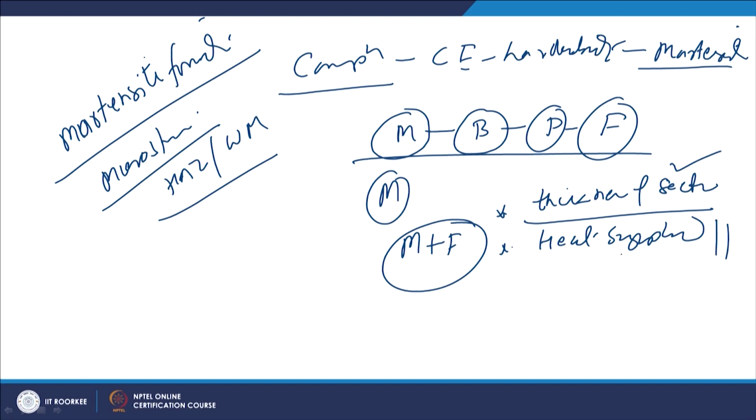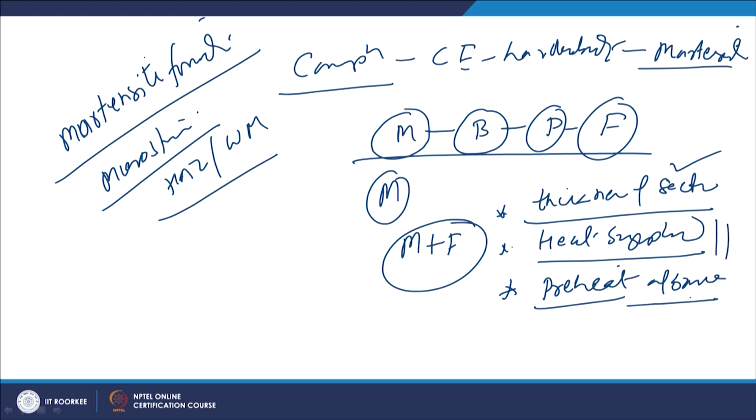On the other hand, it requires greater heat input, and higher heat input in turn reduces the cooling rate. So, in order to keep the cooling rate within safe limits, so that undesirable structural transformations are avoided, we use controlled preheating of the base metal during welding, so that a safe cooling rate is maintained in the weld metal as well as the heat affected zone, in order to avoid undesirable martensitic or ferritic-martensitic transformations.